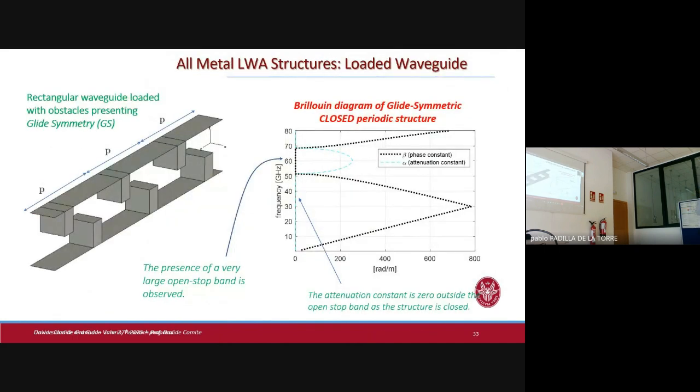And also, how much bandwidth are you going to maintain at broadside? It's a trade-off. Unfortunately, it can be demonstrated that as the bandwidth increases, the gain goes down. But with the tapering, you can get better. Yeah, because the conditions of alpha forbid a narrow one. But yes, that's the point. But as you were saying, when you go up in frequency, the fractional bandwidth is easier. With 5%, it's much better.